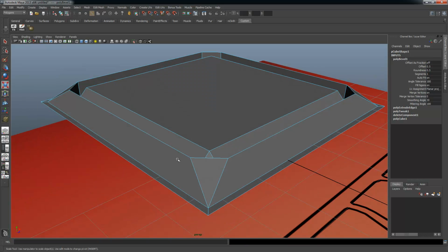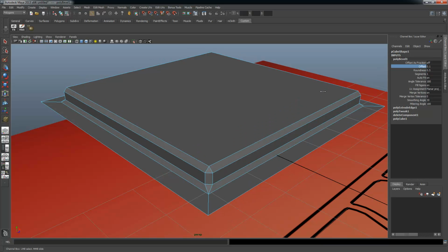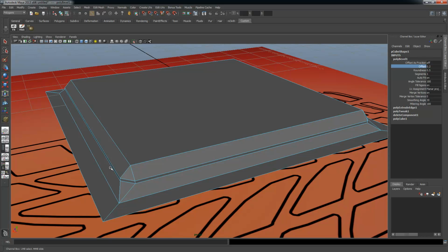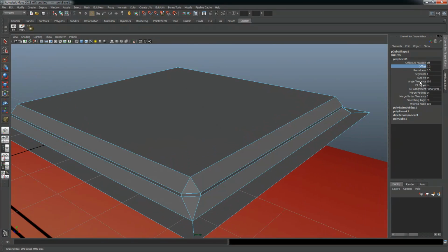And this is kind of weird because it allows you to bevel, and you can actually set the offset so it explodes well outside the bounds of your box. But sometimes that thing is inaccurate and it doesn't let you do as deep of a bevel on it as you want, as well as you may just want to bevel it deeper and then weld the verts or something later. So I like to turn that off.